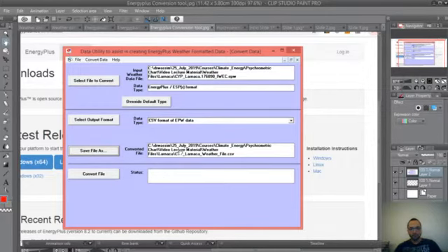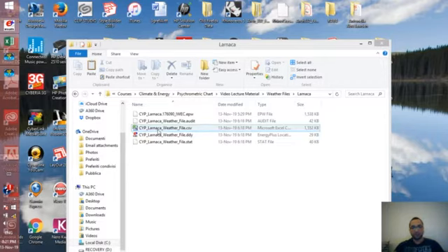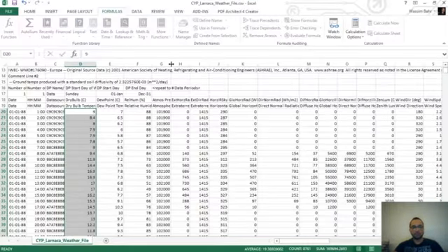You will locate the file name and folder for the output file. The output is .csv, but you will assign a name and a folder for the converted file, and then click on convert file. The process will take less than 3 to 4 seconds. Double click on the .csv weather file. The Excel spreadsheet opens and you are able to see the content of the weather file.